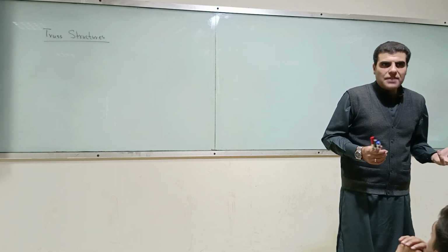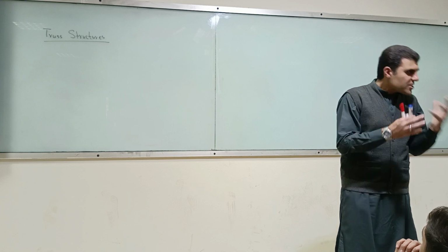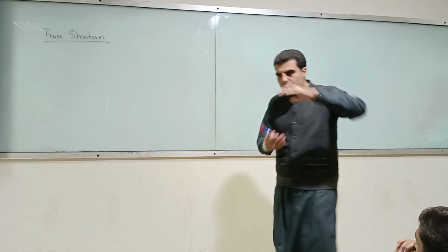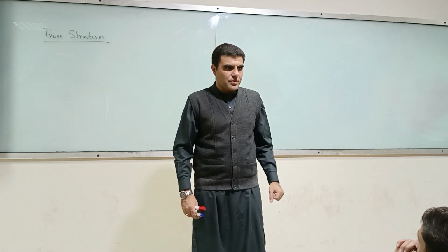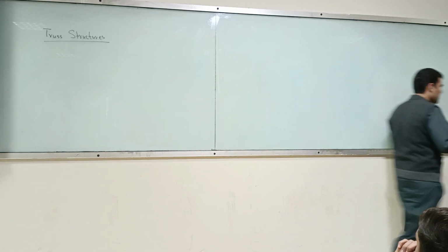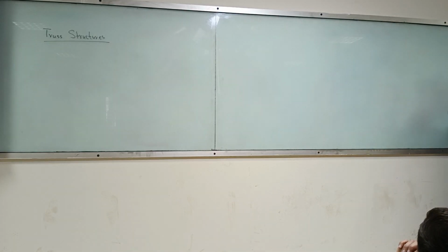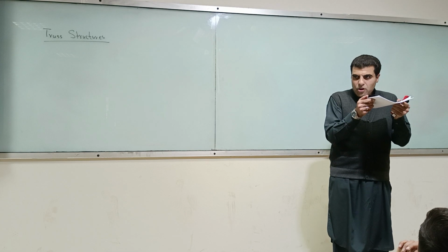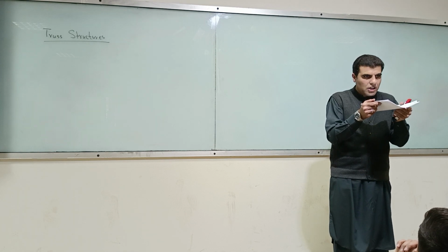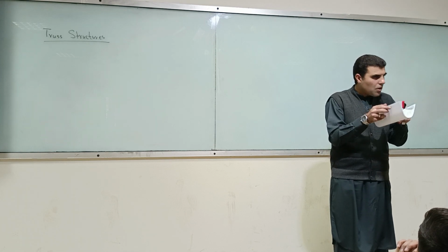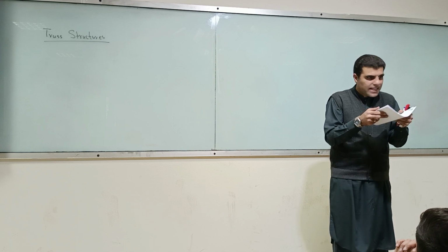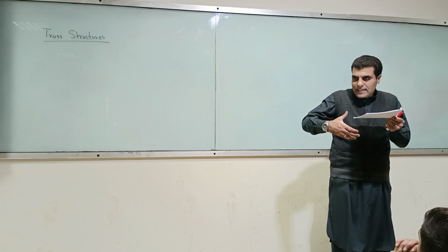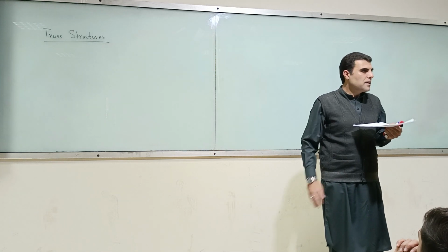Why is a beam of limited span? Because it is solid. If you keep on increasing the span of the beam, you have to increase the depth also. You yourself appreciate that if I have got a very thin structure and I keep on making it longer and longer, what will happen? It will deform. I won't be able to make it stand. It becomes unstable. So I have to make it thicker and thicker as I increase the length.